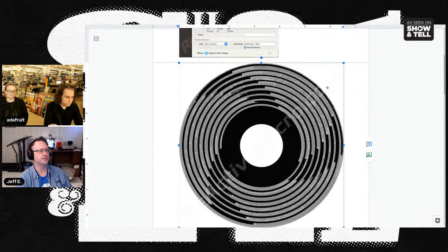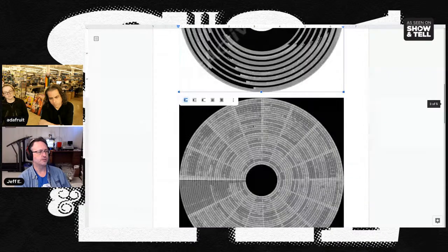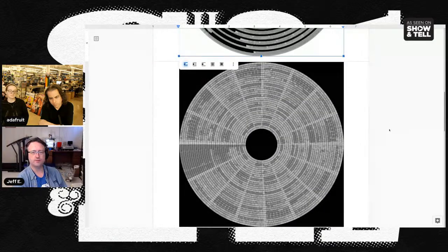This is another one from Applesauce, and it is showing the copy protection scheme of Apple II floppies called spiral tracks. You can see that the data starts here, and then at a certain moment it shifts out, and then it shifts out again. If the software reading it doesn't have the right code to emulate that, then it doesn't work or it doesn't copy. So I wrote some software that does a similar thing, but with files that are written by FluxEngine and Greaseweasel, and it's up on GitHub. I'll put the link in the Discord chat in just a minute.